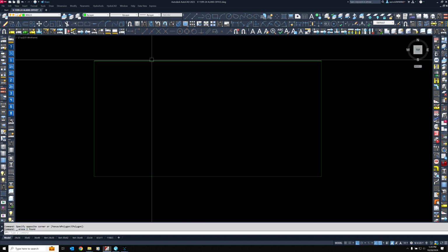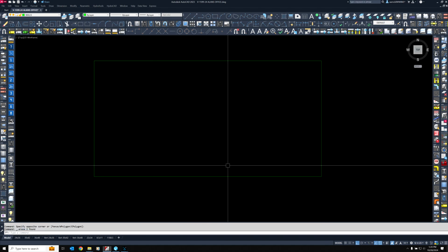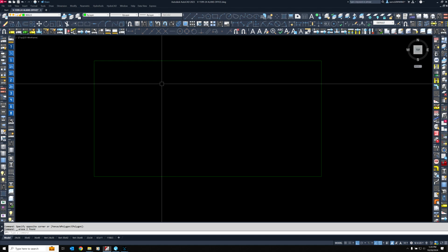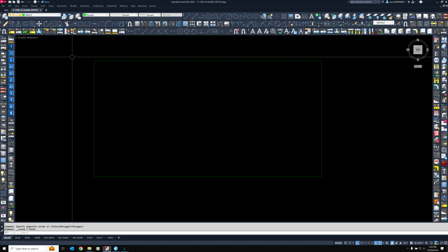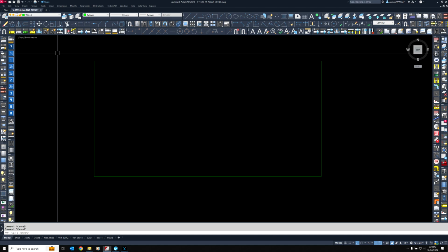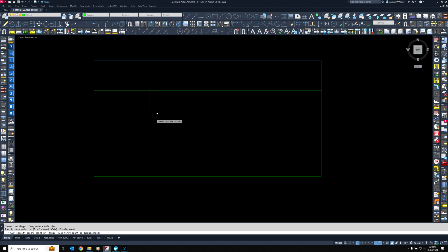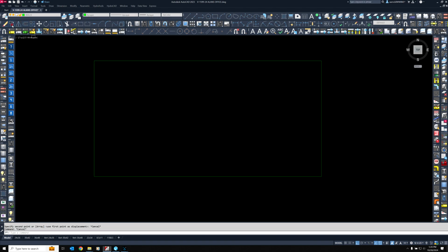So the easiest way to give this the 5-inch wall thickness that this job has, it'll be different on many projects. It might be an 8-inch block wall. It might be block with siding and steel. Nothing's ever really typical. To do this, we either copy or we will offset. One isn't necessarily easier than the other, but right now, left click on Copy, that's this symbol, or you can type the word copy and hit enter.